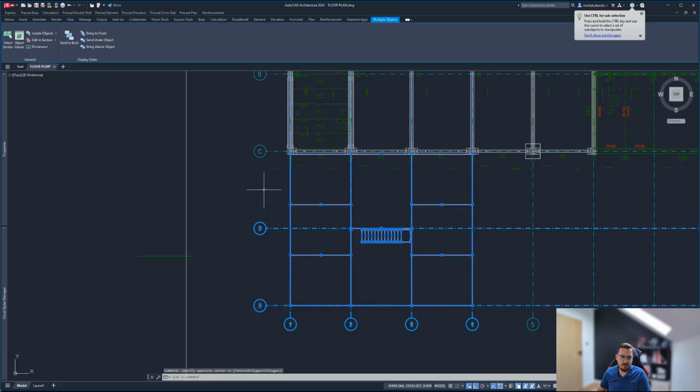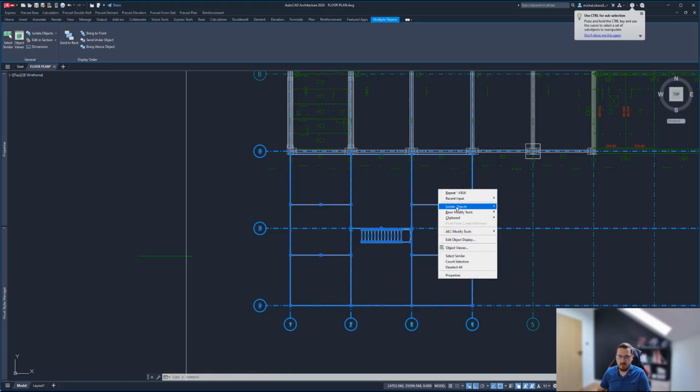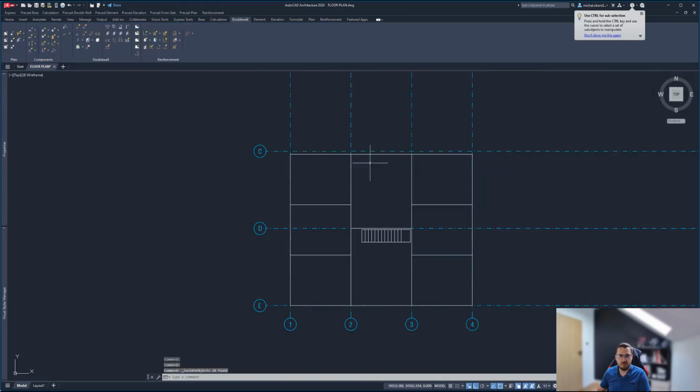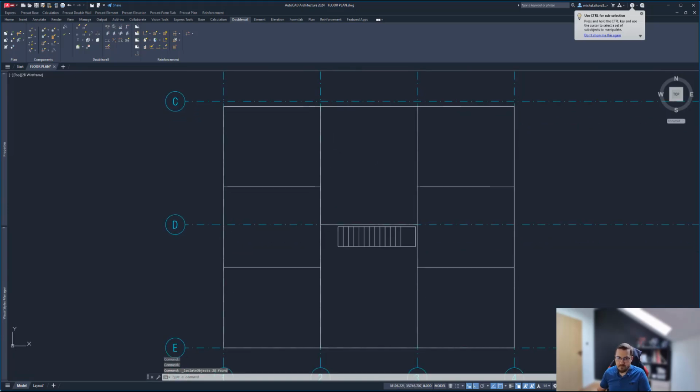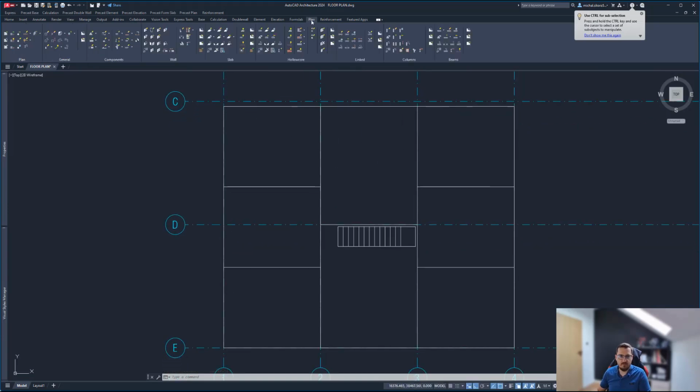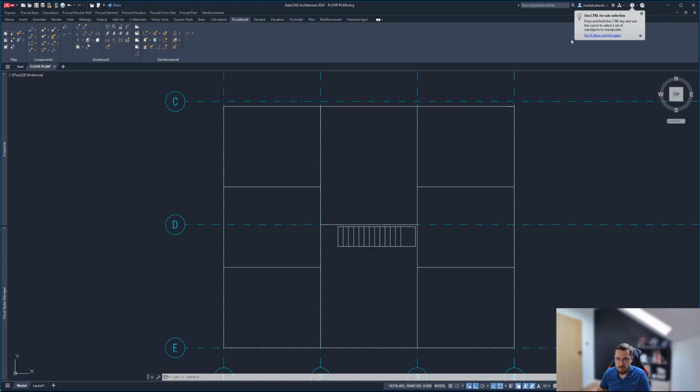What I'll do now is, for the sake of clarity and better snapping onto points, isolate this particular area of the model for us to work on today. Okay, so for your information, in general, for all the other types of elements in Impact, so your beams, slabs, walls, columns, and hollow core slabs, you will be using the plan ribbon tab, because it contains all of those components. For form slabs and double walls, we have separate tabs in the ribbon in AutoCAD.